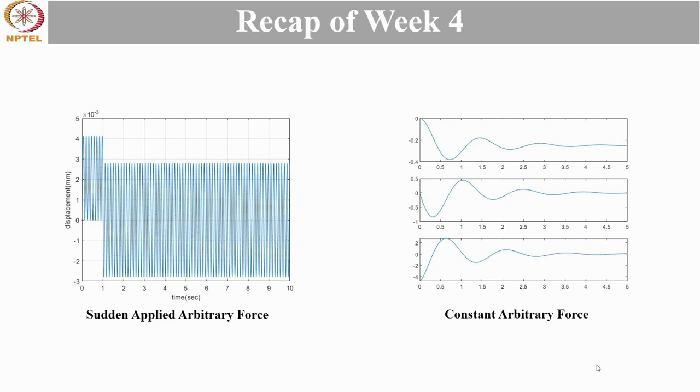The one on the left is the suddenly applied force, where you see initially the force is there in the response, and after the force is removed, the structure is vibrating under initial natural vibration state post removal of force. And in the figure on the right, there is a constant arbitrary force on a damped system where response amplitude was observed to decrease with time.